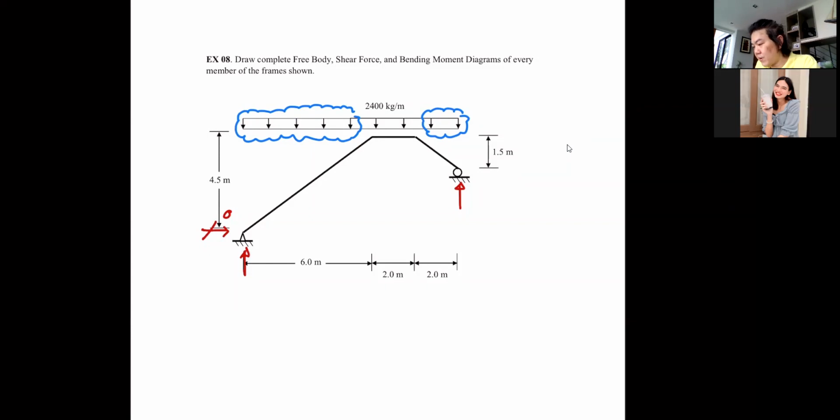And if you recall, we have a determinate structure, so the shape really doesn't matter. So you can do your sigma moment equal to 0, or sigma Fy equal to 0, or you can say by inspection that your reactions should be equal, right?